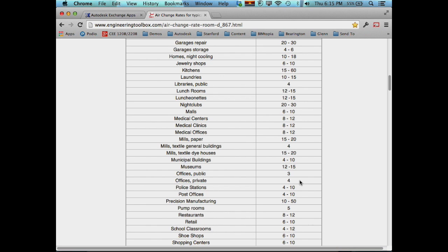Super. Okay, so in order to make that happen, a couple things have to happen. If we really want to change that amount of air in that space, we've got to have two things happening. We have to have some new air coming in at 133 cubic feet per minute. But we can't just pump air into a space, because if we pump air into a space, very high pressure builds up and eventually the doors blow off or something like that. Or the doors actually get very hard to open. If you've ever been in a space where you can't open the doors, sometimes it's just because the air is imbalanced.